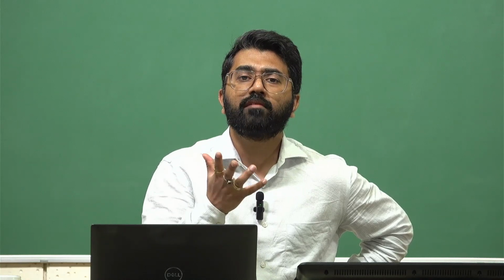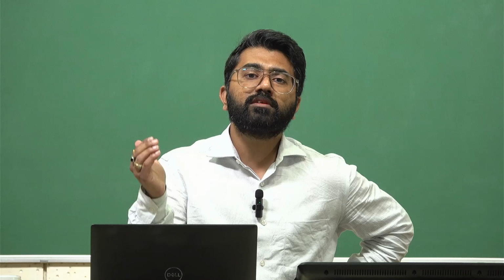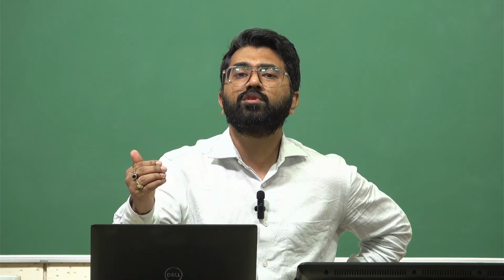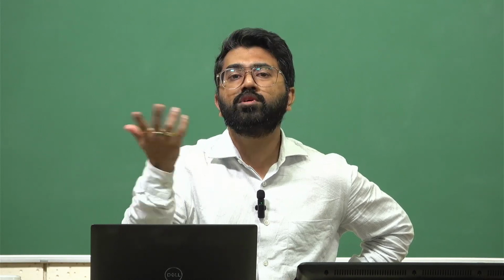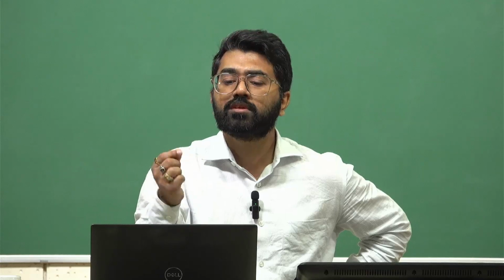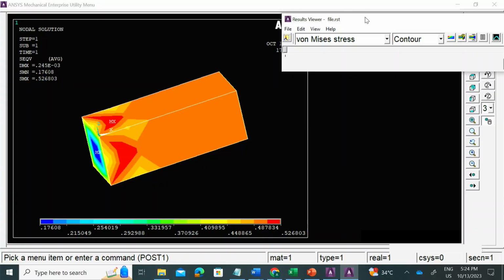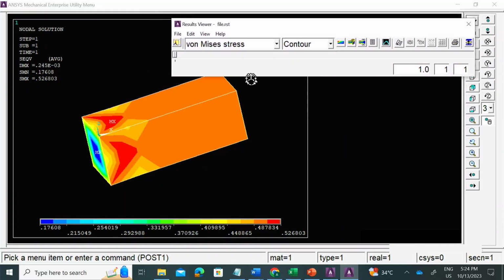This is very important. So theoretically, I can have an understanding that let the stresses not go beyond this point. If it does, I have to reduce the overall load to run another simulation, because if it goes beyond the ultimate tensile stress values, it is going to fracture or rupture somewhere, right?